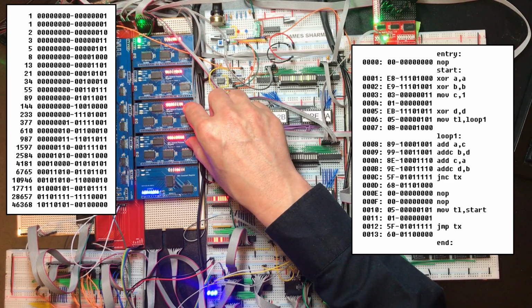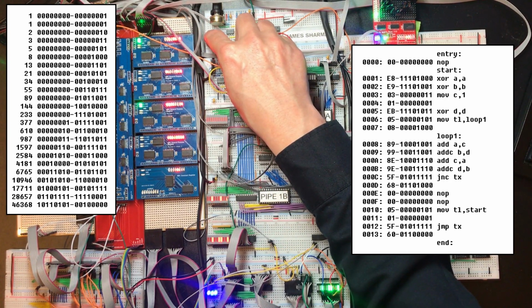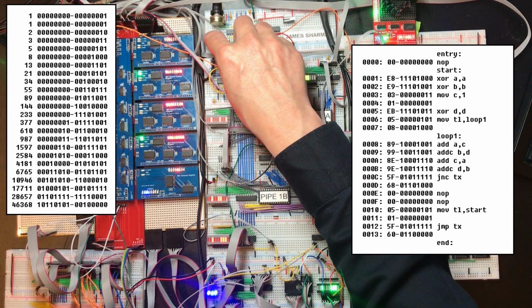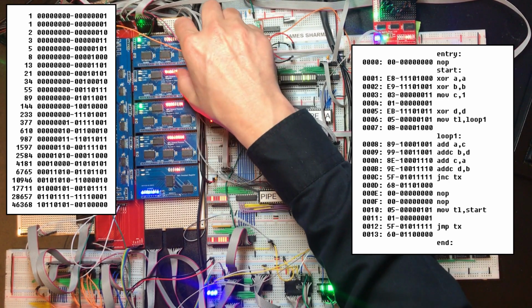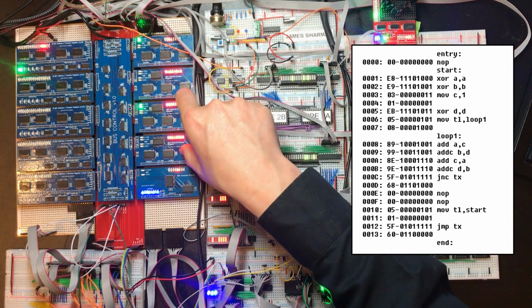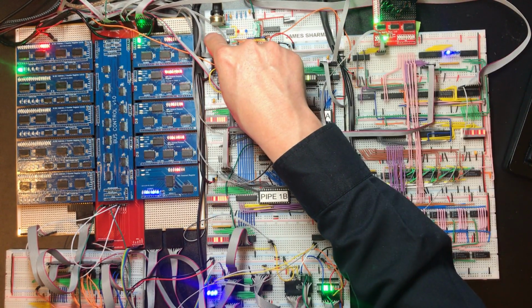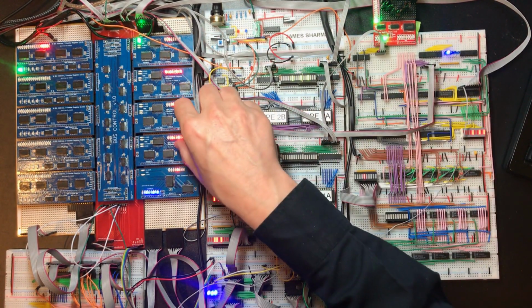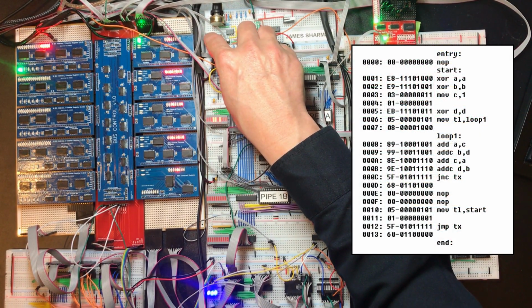So then that is 28,657. So looping back around. 46,368. This is the largest Fibonacci number we can fit into a 16-bit variable. So now we're going to add that to 28,657. And the carry flag is set because the result didn't fit. And the jump didn't happen.